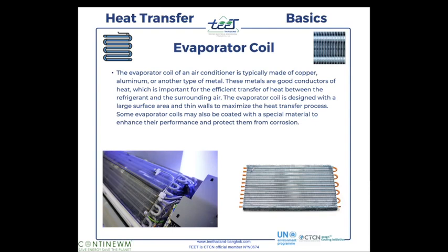In the opposite, in winter in Europe, they use heat pumps. So they take the heat from outside, even if it's cold, and they put it inside. So it's a heat pump in one way or another. And the air conditioning in Europe in general works both ways. You can select the heating mode or cooling mode. Now, heat pump is the process part. So you take the heat from one part of the building to the other part, inside to outside, or outside to inside.